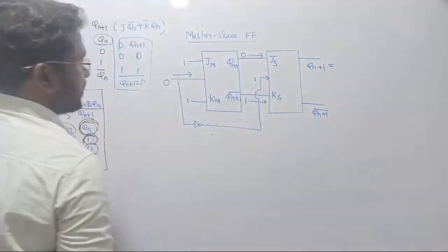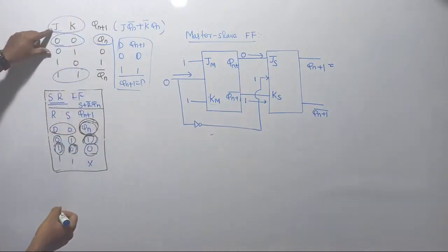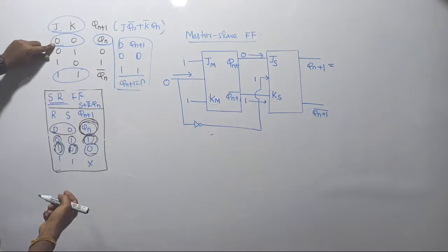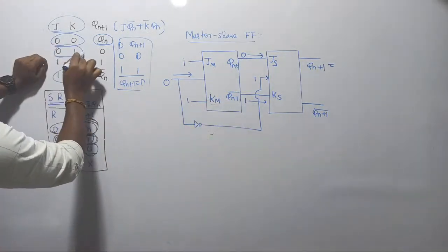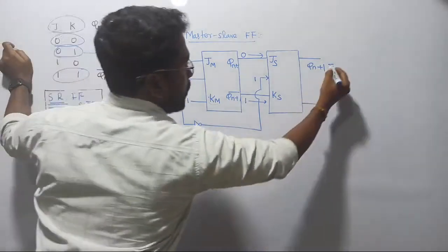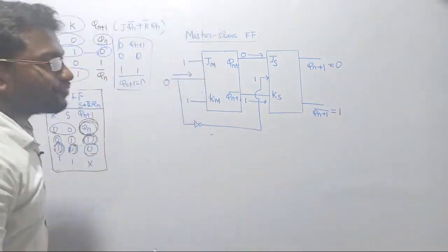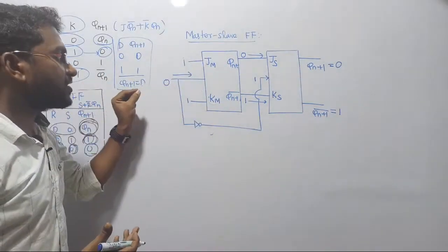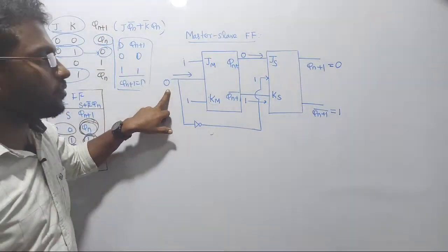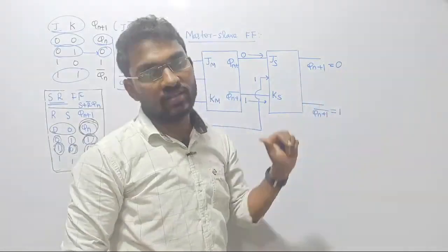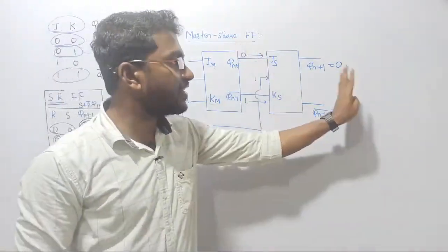While passing 0-1, see there, this is JK flip-flop, right? When your J value is going to be 0 and K value is going to be 1, 0-1, its possible correspondent output is going to be 0. If it is 0, automatically here it will become 1. That's all. Now the thing is, until you apply the gate pulse here again, there will be no changes in the output state of this circuit. It won't toggle, it won't go like 0-1 0-1. That state is not possible.